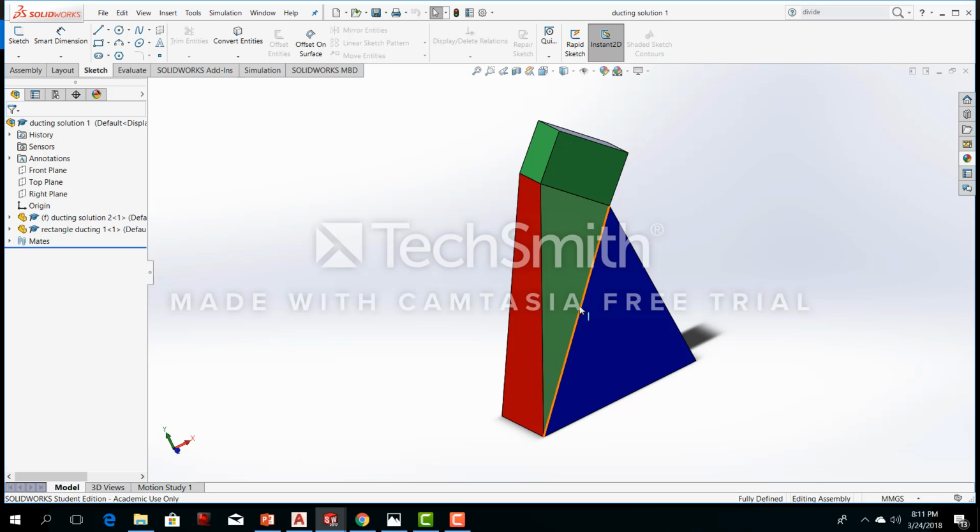Okay, so this fold line would turn our warped surface into two triangles, and the two triangles are on plane surfaces, which means they can be developed. So we could have developed these two surfaces. However, now that I brought this into a problem-based task, I want the students not only to be able to tell me the principles of why this is going to work, but I want them to explain why they think that we should choose this over adding another piece onto the top of our main transition piece.